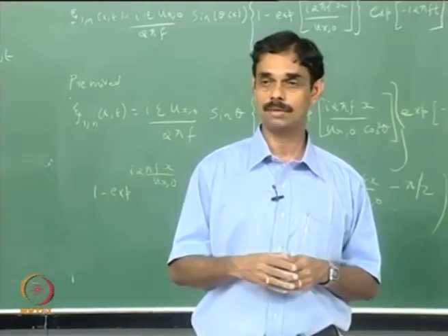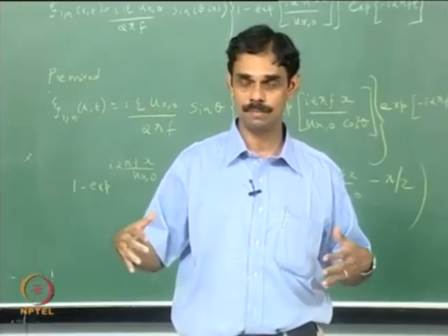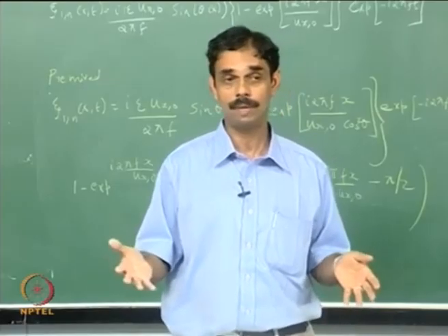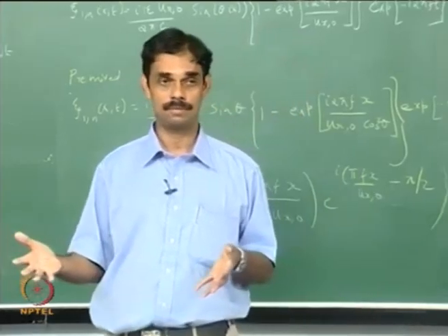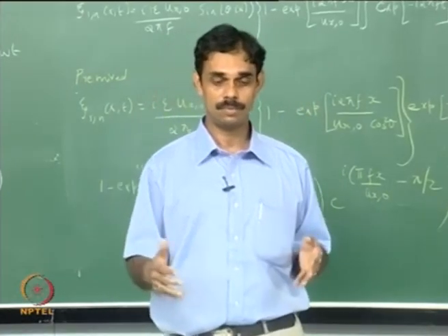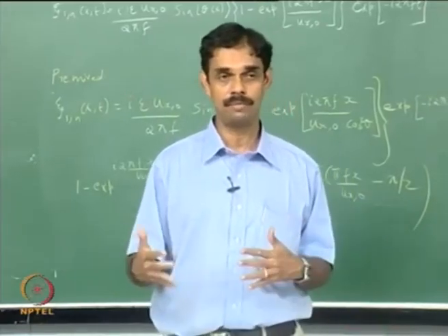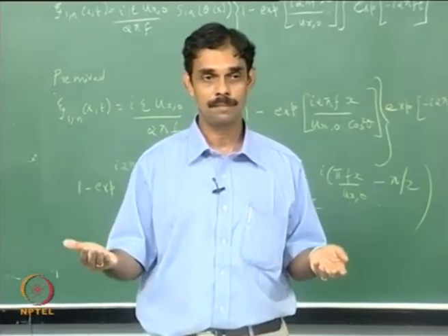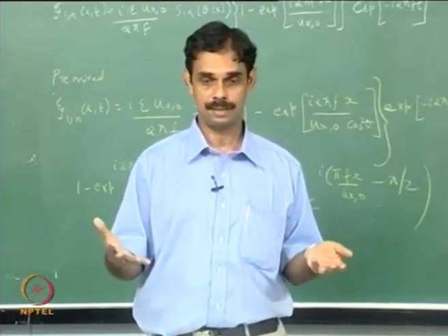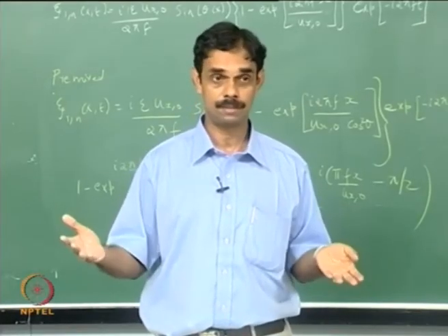But central to this calculation is the input to the model, which is the flame response, how the flame behaves in response to the fluctuations, and we have made models for several different systems. For example, just now we did diffusion flame, earlier we did a premixed flame, and we have studied a lean premixed prevaporized flame.